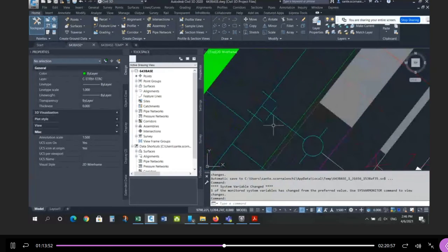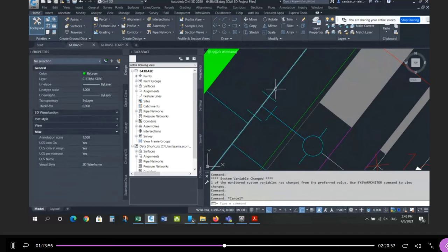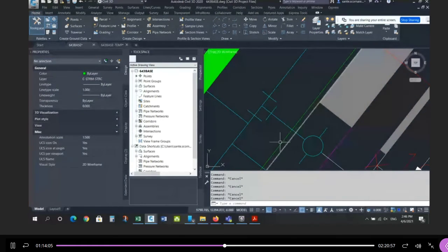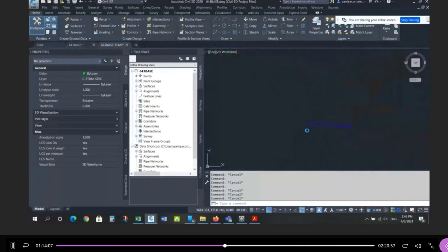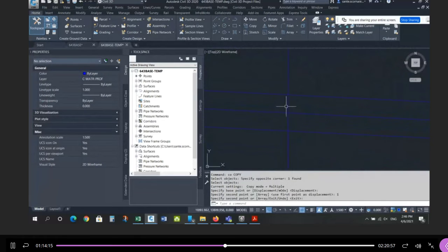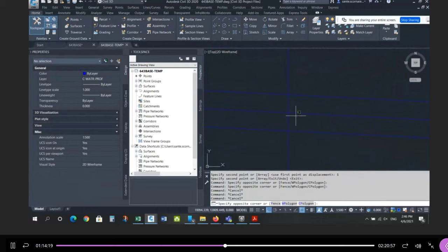According to the standard, this pipe here is always a 150 pipe. Okay, doesn't matter what the main is, the pipe that goes to the hydrant is always 150. How do I know? Look at the standard in Halton region. Okay, so I know that's a 150 pipe. So how do I draw that in profile? Well, so I know this is the hydrant. Again, I'm going to make a copy of this straight down 1 meter to the middle of the pipe, and I'm going to draw an ellipse right there. Okay, remember, this is 200. I want a 150. So I'm going to offset 0.075. There's the sides of the ellipse.